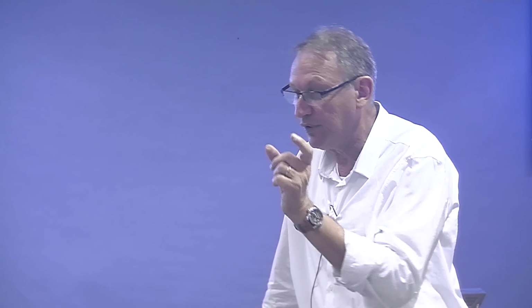I mean, let's say you have a separation from your wing in that tunnel, and during the separation there is one eddy and another eddy, and in 3 milliseconds you pick up only one eddy or 1.5 eddies. It's not enough to get an average feature of what's going on.